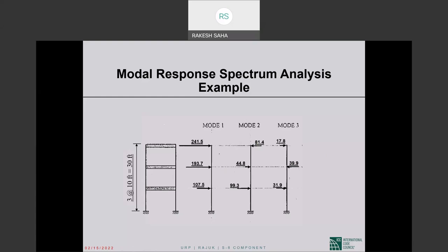The answer is no. If we combine these floor level forces, we will lose the signs. As soon as you square something, the sign is lost. So the fact that this is directed this way and that is directed this way will be lost. And that is vital to calculating properly what we need to calculate. So the only way to go, there is no shortcut.